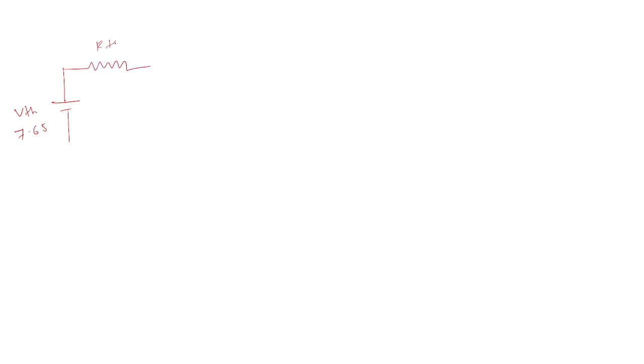What is the value of RTH? 6.72 ohm. I hope that you know we have removed RL from point AB. We need to connect that RL one more time. So RL is equal to 10 ohm. So what is asked? Voltage across 10 ohm. Now simply see. First of all, we need to calculate the value of current.